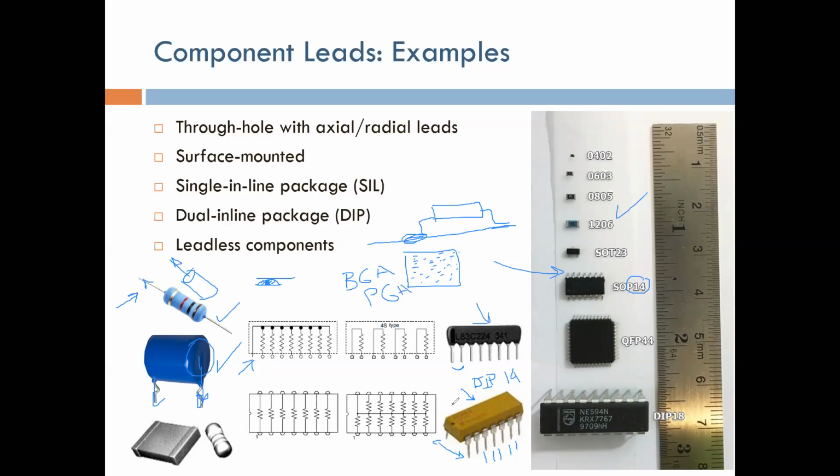Okay, you can also have dual inline package resistances where, for example, each 2 opposing leads will have a resistance between them, or you might have all of them connected to resistances, and one of them is common, which is also used in some applications. So it depends on the application that you are using. You can choose any one of these. Sometimes it's a good idea, if you're using a lot of resistances, to choose one of these packages because they are much more integrated, and the matching between the resistance values will be much better than getting discrete components individually. Okay.